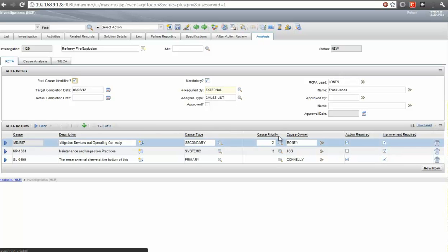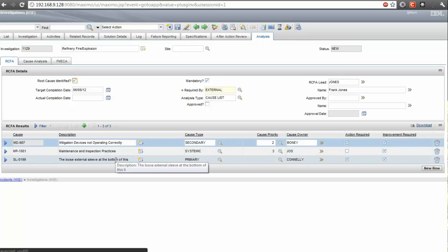Now, often from this point, what I will do is usually go to management of change, because before you make a change as significant as removing all old sleeves and installing new sleeves, you're going to want to do some type of due diligence. You're probably going to look for funding, do a risk assessment, get proper approvals, and some pre and post start actions. So that is definitely part of the story. But there is a follow-up slide presentation video that focuses primarily on MOC, and it will fit very well into the story at this point. So you can definitely watch that one. I keep it out just to keep time down on this one.